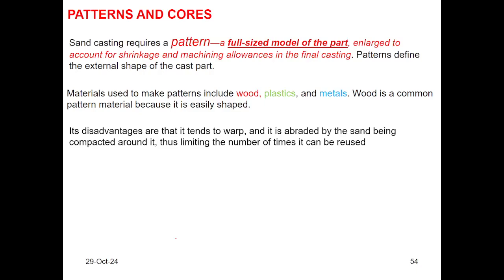Metal patterns require first wooden models, wooden patterns, and then the casting stage, so in the end we have a metal pattern. Since metal patterns are cast, they require an additional manufacturing process beforehand. So metal patterns are correspondingly more expensive. But the advantage of a metal pattern is that it can be used not only one time, we can use it more times.